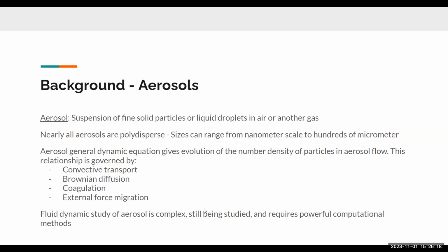This difference in size, as well as a few other things that govern the flow, makes the study of aerosol flows pretty complex. This general dynamic equation, which gives the evolution of the density of particles in the aerosol flow, is governed by the convective transport or bulk flow transport over time, but also Brownian diffusion, the coagulation of the particles, and any external force that acts on the flow. So the flow dynamics of the aerosol is very complex. It's still being researched and requires powerful computational methods to study its flow dynamics.